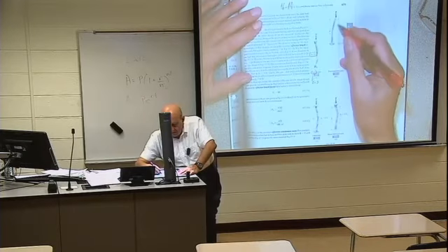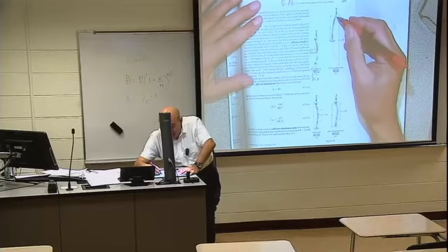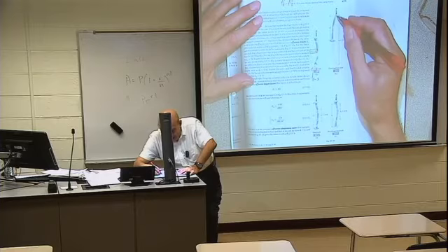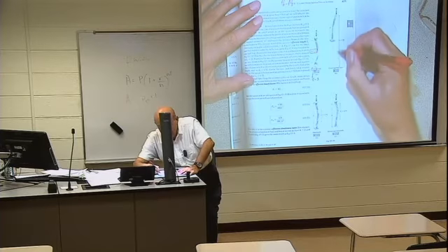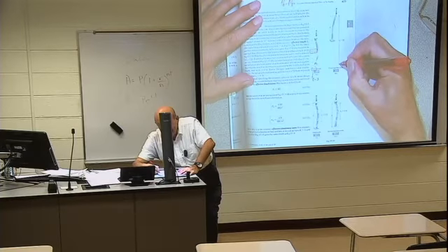Now, for clamped free, then pay attention. Actually, we can consider that a clamped free beam is half of the simply supported beam of length 2L. Okay?